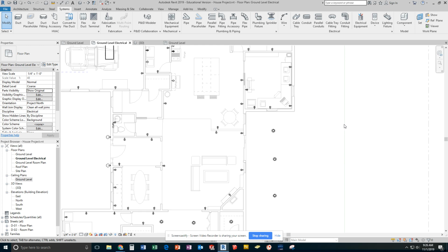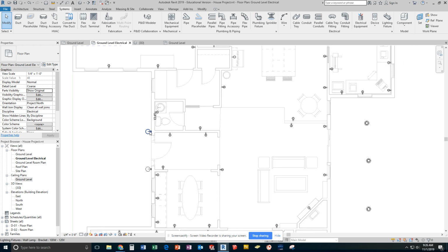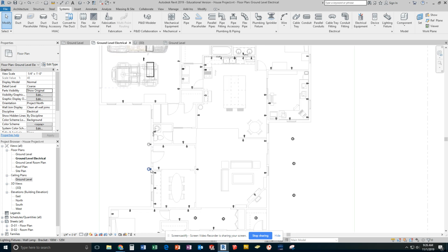Now, just for reference, when you start doing switches, I would account for these by putting a switch likely near this back door here so that you would be able to turn those lights on as you exited out onto this back deck. Same thing with the porch lights out front here. I'm probably going to put a switch right in here, and that's the one that's going to get wired to those porch lights. Okay. This is in a spot too where I could add a ceiling if I wanted to and either leave the porch lights or add the overhead lights. It would be my choice, as it is yours, to how you continue the rest of this. We'll come back after I've finished all this and talk about switches and getting ready for circuiting.